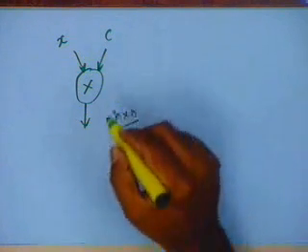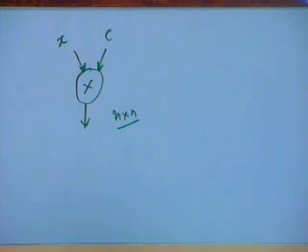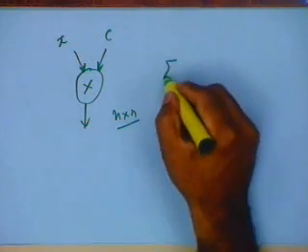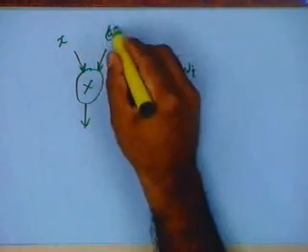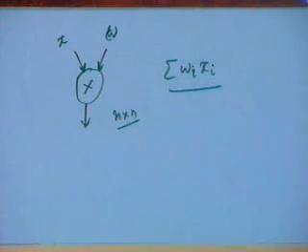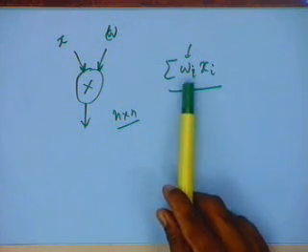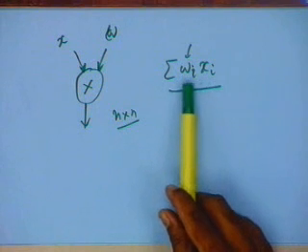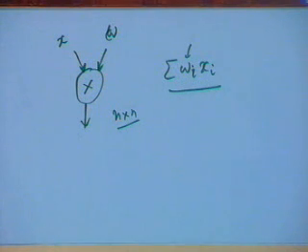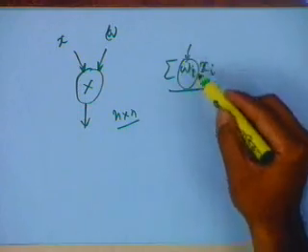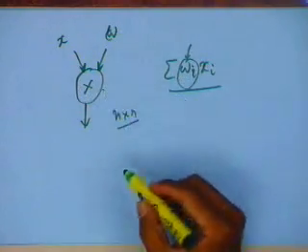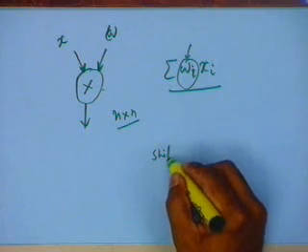which is very true in case of DSP, because you are implementing equations like wi xi, a very common operation where you have some weights, whether you are doing a discrete cosine transform, filtering and so on. These are very common operations where you are weighting the numbers and adding, first multiplying and then accumulating. So if I take this multiplication and replace it by shift and add,